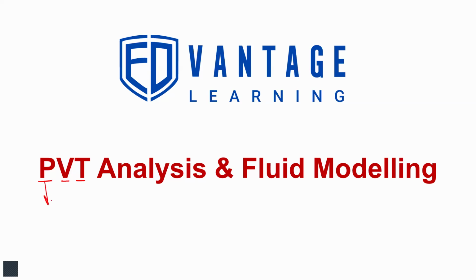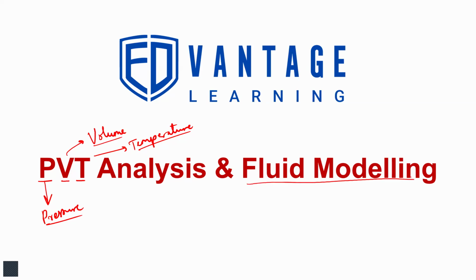Okay, so P is pressure, V is volume, and T is temperature. So with this analysis, we try to understand the relationship between pressure, volume, and temperature of any fluid. In the oil and gas industry, it is for hydrocarbon fluids. By analyzing that relationship, we build a fluid model that works at all pressures, temperatures, and volumes of the field life of production, right?